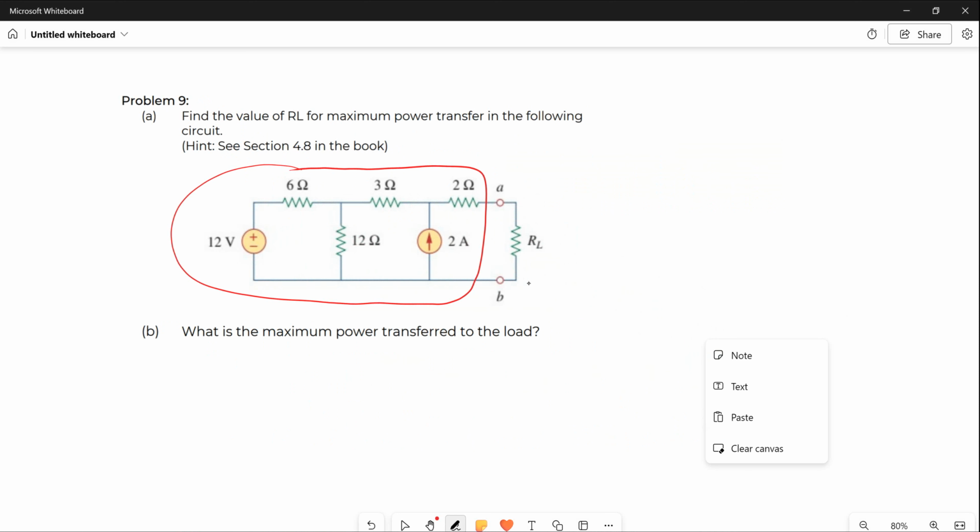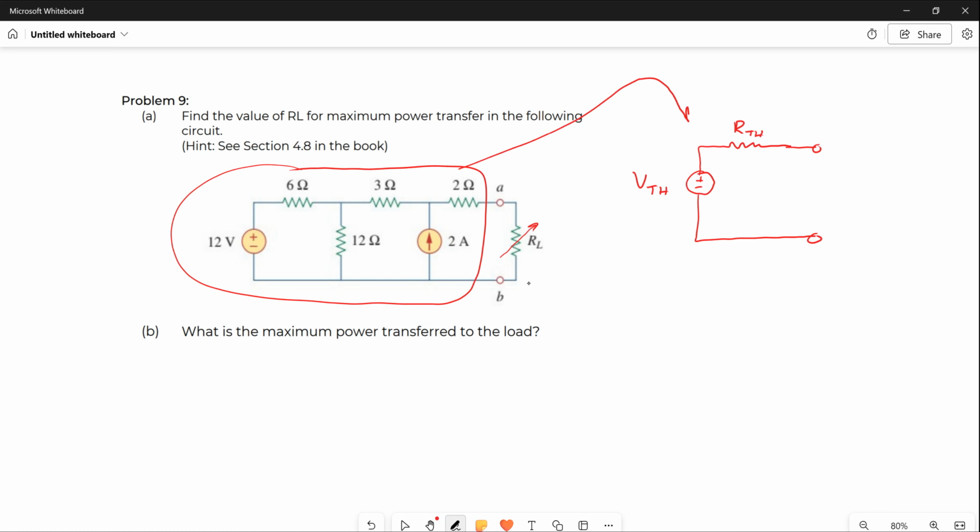In other words, if you vary that and you have your Thevenin equivalent circuit that looks like this. Now, we didn't find the Thevenin equivalent, but let's make this V Thevenin right here. And let's say we calculate the Thevenin resistance up here. We're going to do that in a minute. There's your Thevenin resistance. And then you put your load resistor on out here. So that whole circled part of that circuit, I reduced down to a Thevenin equivalent. And then I put this load resistor out here.